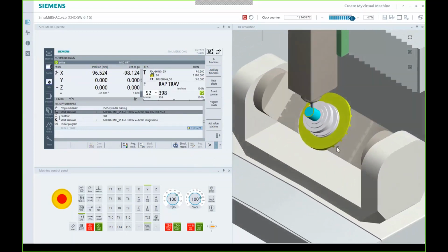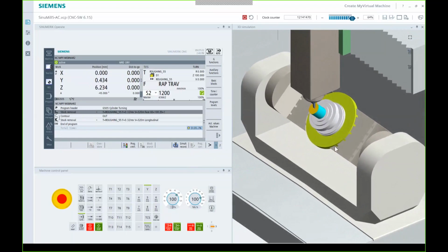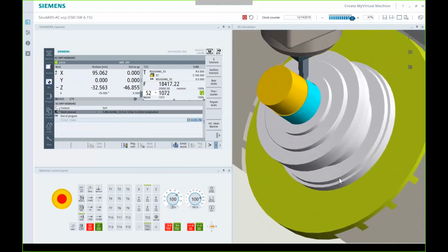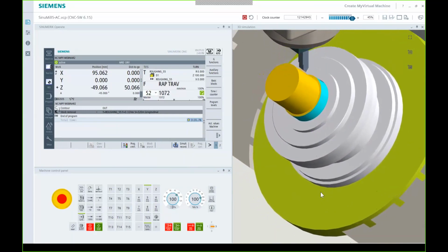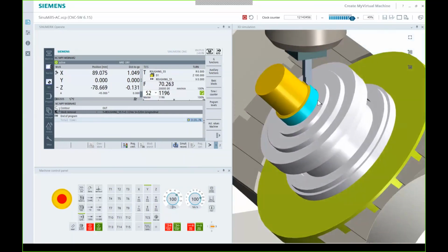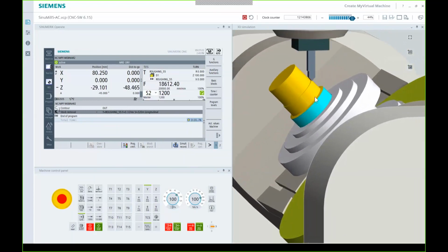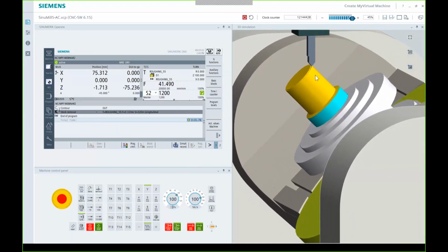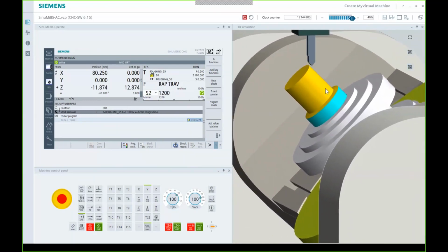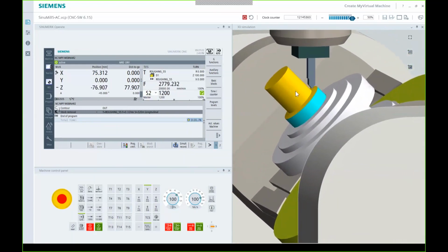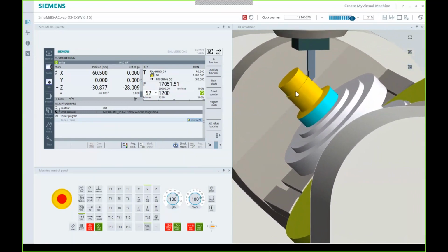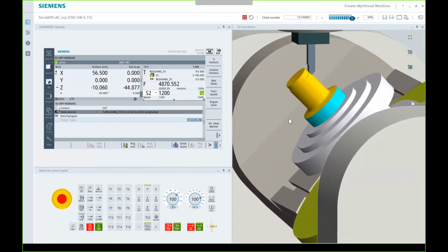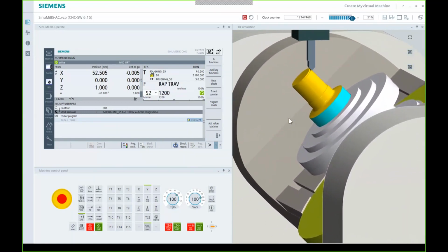And it'll begin cutting my facing operation. And my handle B. And you'll see the same thing, but here I can actually visually see the tool and the angle that it's held at, that it's not going to be able to get into that undercut, but it will cut what it can. We're going to use another cycle to finish off the rest of that.